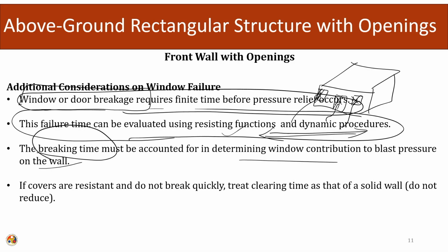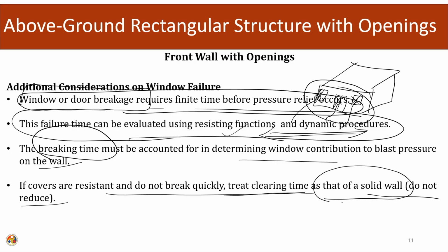If covers are resistant and they do not break quickly, the clearing time should be treated as that of a solid wall. It will not reduce, because a significant amount of time would have passed, and the blast loading would have been engaged by the entire surface. So that this becomes equivalent to a solid wall. So, the treatment of the clearing time depends upon all of these factors.